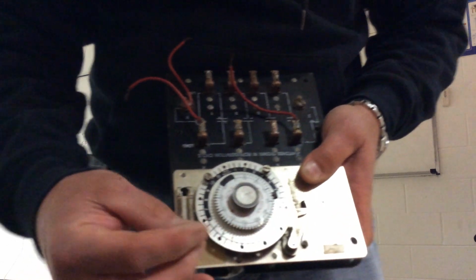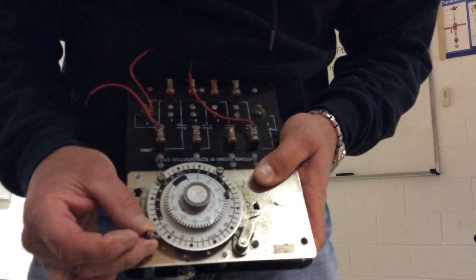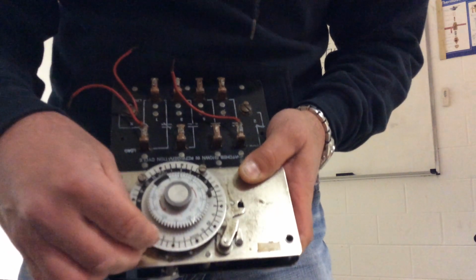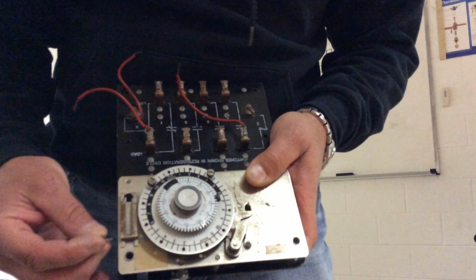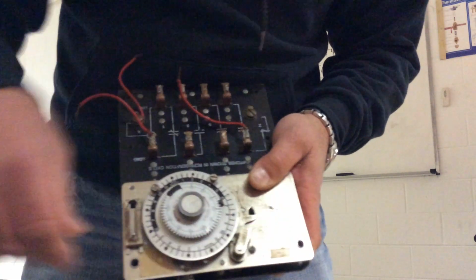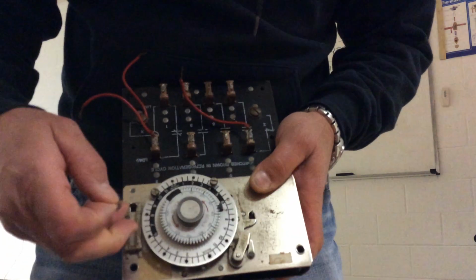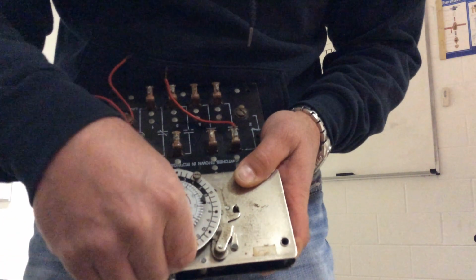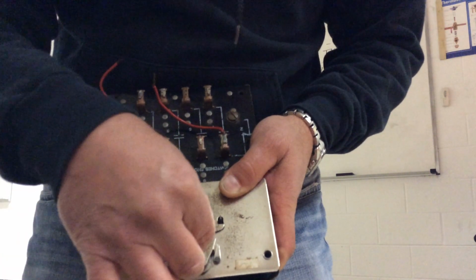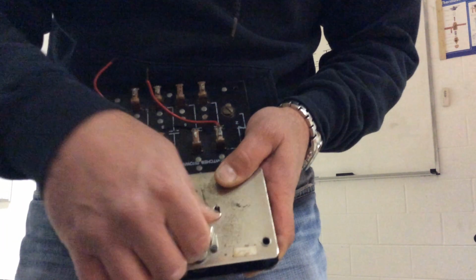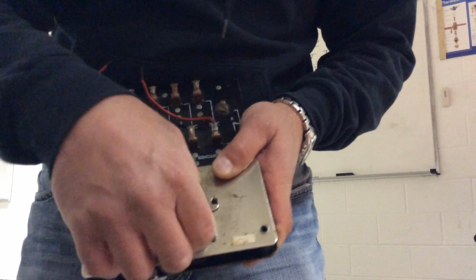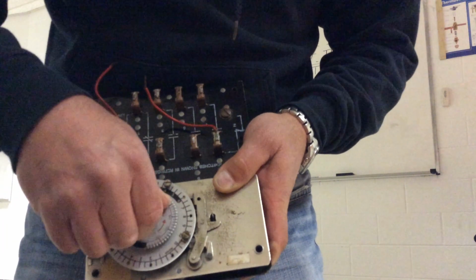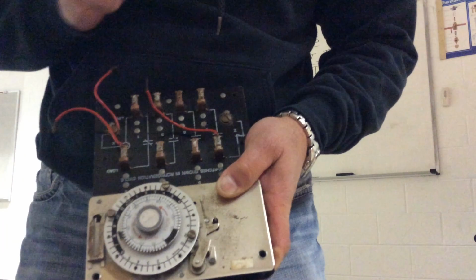Now these also have designation pins. What I mean by designation pins is they designate the period of time when we need to go into defrost, and we can set that whenever we want to. We can take these little pins out. Usually they're in a carrying case right here. We can take one out and screw it in at the time that we want it to go into defrost. If we wanted to go into defrost at 10 a.m., we could screw a pin in there. And then as this clock sits there and turns, it would come to that pin and put us in defrost.